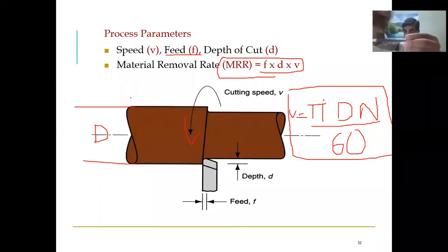So at what speed are we moving this? The workpiece may be rotating at a very high speed, but we don't move the tool at such a high speed. Maybe in one minute we move only 10 mm, slowly, because the workpiece is rotating. So how and at which speed we are moving: something about 10 mm per minute. This 10 mm per minute movement is called the feed. This rotation is called the speed, and whatever this movement is, that is called the feed.